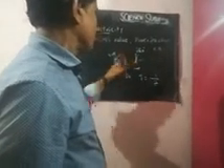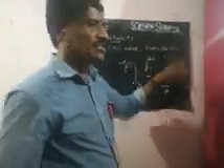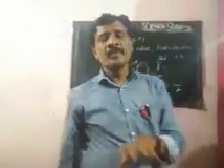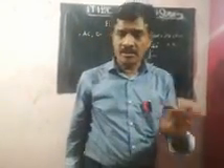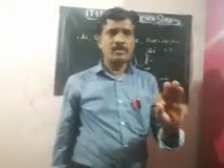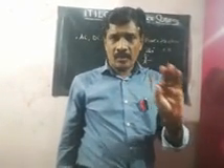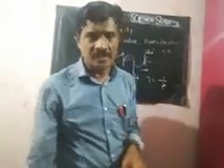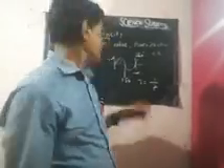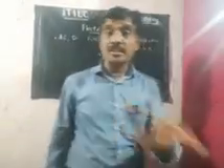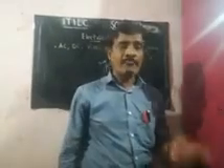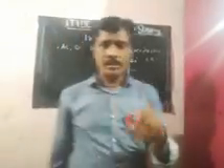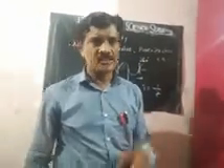After 360 degrees, the same process occurs again, just like the wave starting from 0 to 360 degrees. That's why, in alternating current production, the energy flow in a definite interval of time repeats, and that completion of time becomes one cycle. Here we have taken the example of 0 to 360 degrees as one cycle. By formula, the time period is calculated by 1 by f. Here 1 by 50 means 0.02 second is one cycle.